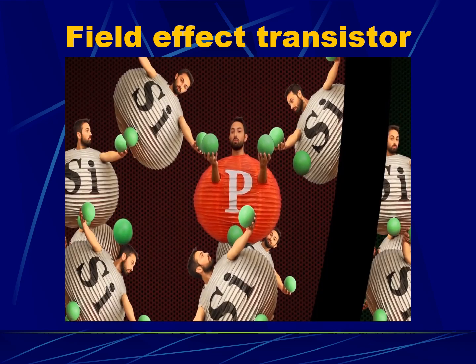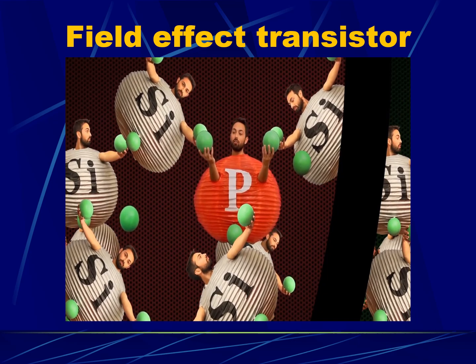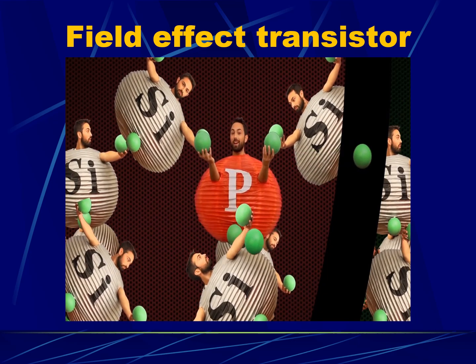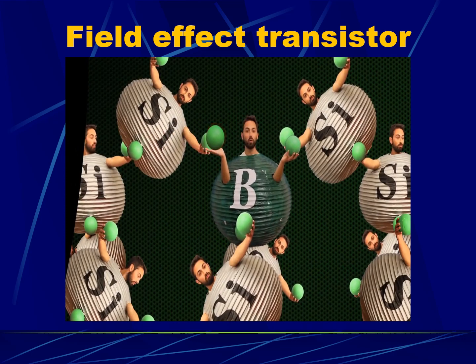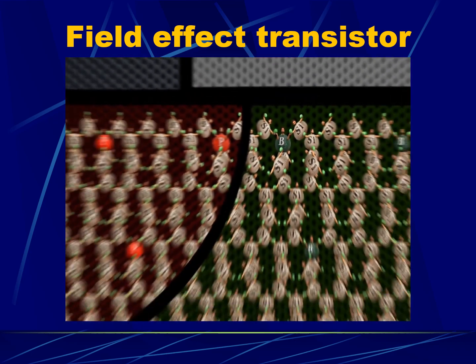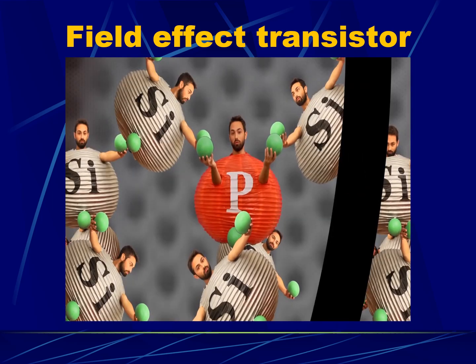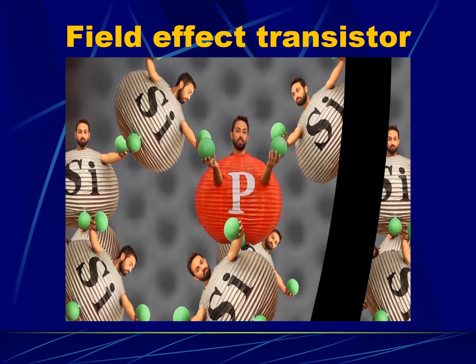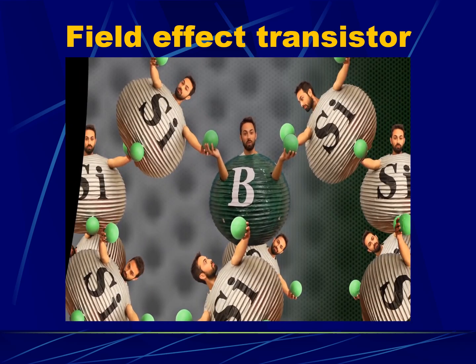When a transistor is made, the N and P types don't keep to themselves. Electrons actually diffuse from the N type, where there are more of them, into the P type to fill the holes. This creates something called the depletion layer. What's been depleted? Charges that can move. There are no more free electrons in the N type. Why? Because they've filled the holes in the P type.